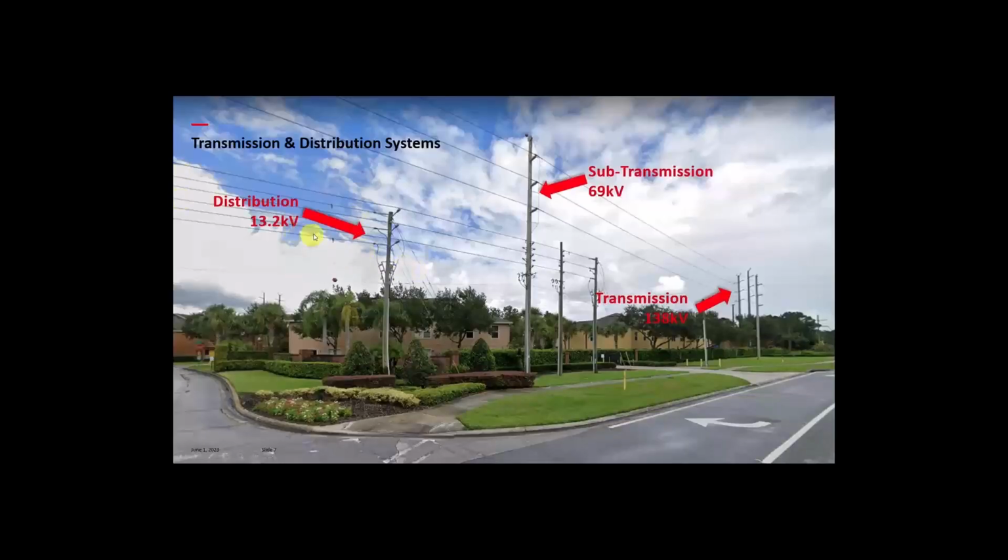And part of it is more than likely going to be overhead, especially if you're in a suburban type area, not high density. Then when it transfers to underground, this is what it's doing here: it goes from an overhead line, connects up with some fuse cutouts, and goes underground. And this is nice so you can compare it to what utilities refer to as sub-transmission. These are the circuits that go from substation to substation. They're not really long-haul transmission, but they're there to interconnect local substations together.